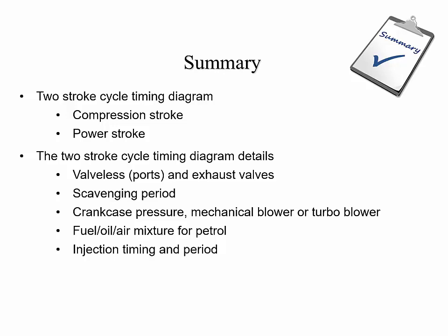The period of fuel injection is related to the size of combustion and the power demand. So the more power we demand, the more fuel we need to burn, the longer the injector injects fuel. There is a limit, however. There is only so much air available with oxygen to burn fuel. So there is a maximum amount of fuel that can be burned in a certain combustion. Right, that summarizes the two-stroke cycle for this lecture.